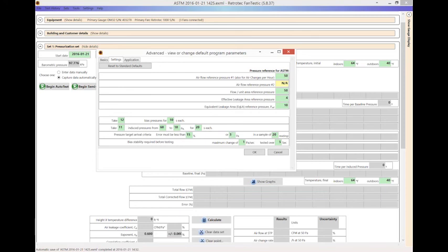All right. So that determines when you can actually start gathering your data, and within a sample of 20 of them. So it says within 20 readings, if I'm this close to my test pressure, I can gather my data. And these are the defaults. The other one is how stable does my gauge need to be in order for it to begin testing or do my baseline, which means that I need to have a difference of 1 pascal over 5 seconds. So you can't have your gauge fluctuating with pressures in order to do your baseline. It really wants to make sure your gauge is stable before it does a baseline or starts your test.